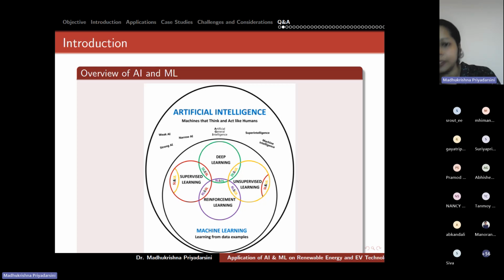So taking the image itself from the environment, it is analyzing, for this kind of food, what the cooking time is. Inside the programming, the threshold limit is set. For example, if you are heating a product, maybe 1 minute or 2 minutes is enough, so in the threshold value, that 1 minute or 120 seconds is mentioned. Then when the picture comes to the chip, it analyzes and finds out whether the value is less than the threshold value or not. If it is less than the threshold value, then it gives another stimulus response to the hand of the robot, the sensors present in the hand of the robot, to switch off the microwave.